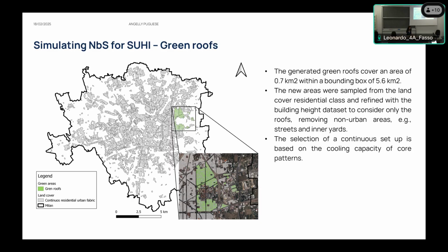So I took a neighborhood, put it on top, and sampled the dense residential areas. I masked them with the buildings, because even if the DUSAF is quite precise, within a house or building we can still take backyards or some streets. So to be very precise, I masked this with the building height to exclude anything with zero building height, to take into consideration only the built-up areas.